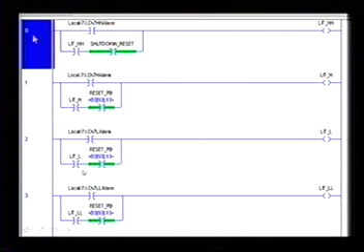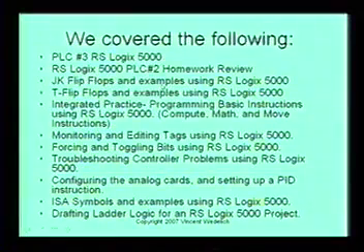And then we had an LAL, right? It's an alarm as well. So it's just a reset button. We'll reset it. It doesn't shut the system down. And then we have a low-low. So technically this is a shutdown because it was an LSLL. So that shutdown reset should have been down here as well, because you don't want to be able to reset this unless the entire system is shut down. You've allowed the whole system to stop.